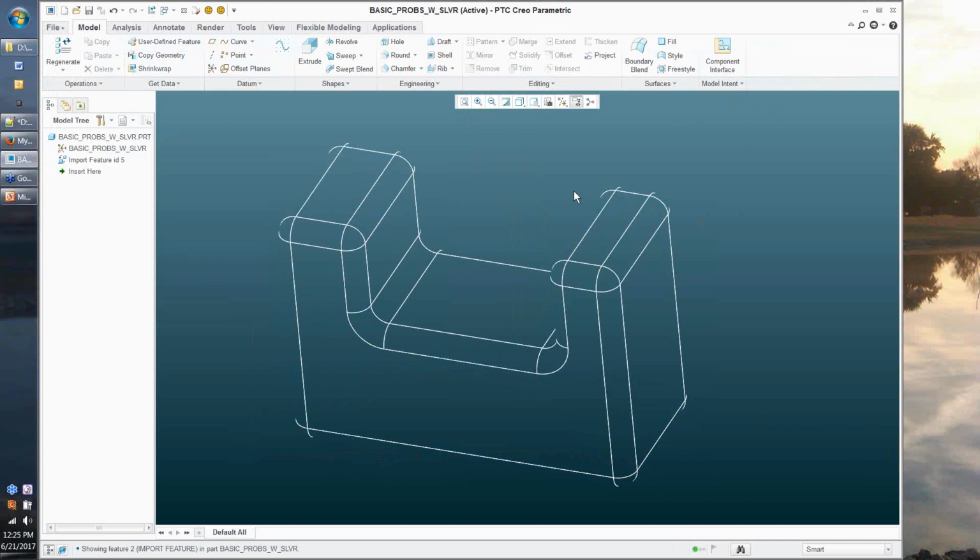Now, when you decrease the accuracy by increasing the size of the number, it typically does not make the part fall down in such a way that you get additional errors and additional problems with the imported geometry. Sometimes it can be helpful to increase the value for accuracy to be able to repair a very problematic file. However, by doing so, you are relaxing the declaration of the topology.